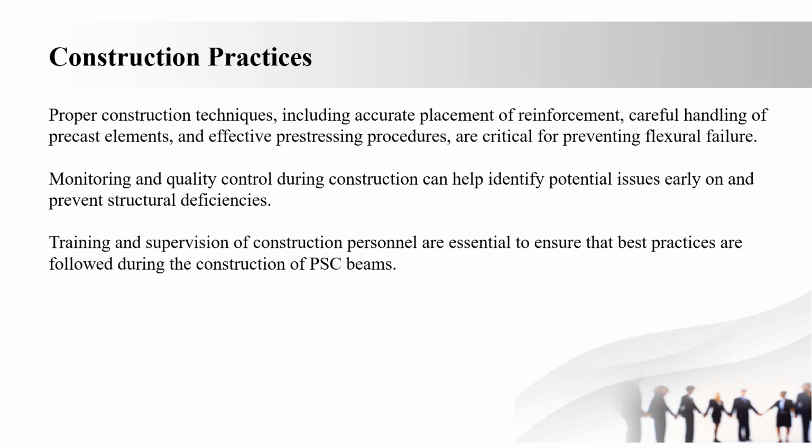Now the construction practices. Proper construction techniques including accurate placement of reinforcement, careful handling of precast elements, and effective pre-stressing procedures are critical for preventing flexural failure. Monitoring and quality control during construction can help identify potential issues early on and prevent structural deficiencies. Training and supervision of construction personnel are essential to ensure that best practices are followed during construction of PSC beams.